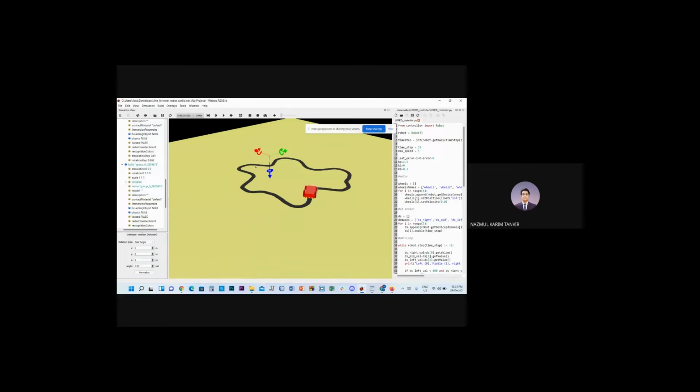For this line which I added, we have to go to the File and the Import 3D Model section. As I already added the line, I am skipping this part, and for this line we have set different values accordingly. We have set the rotation values x, y, z: x is 1, y 0, z 0, and angle 1.57.